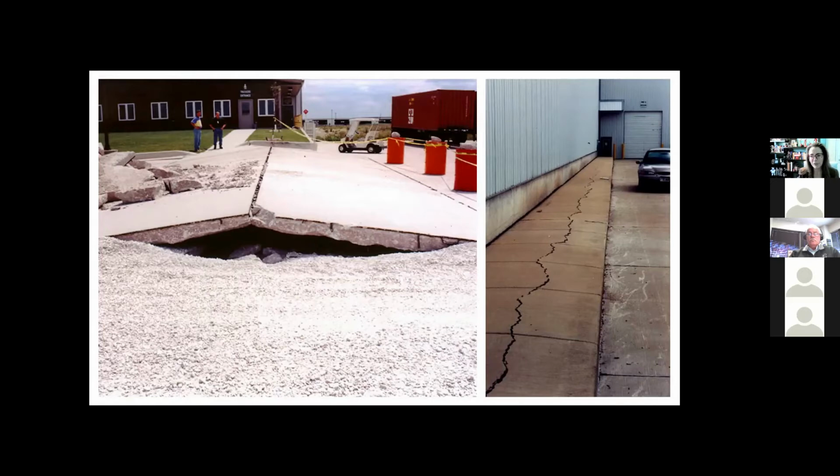They also give our public their view of concrete. So we need to build them to a higher standard in our communities. But in this instance, the sidewalk did us a service. What happened here is there's a parking lot and it needed some expansion joints, but they didn't put them in. So when the concrete heated up, it expanded and it pushed, and that was several inches of expansion. And the sidewalk, being weaker than the pavement, was kind enough to relieve the stress by cracking and faulting.